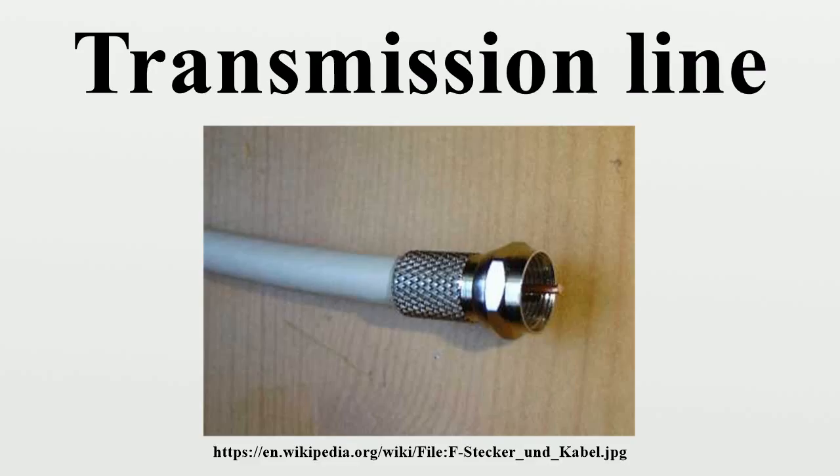Twin lead consists of a pair of conductors held apart by a continuous insulator. By holding the conductors a known distance apart, the geometry is fixed and the line characteristics are reliably consistent. It is lower loss than coaxial cable because the wave propagates mostly in air rather than the thin dielectric. However, it is more susceptible to interference. Lecher lines are a form of parallel conductor that can be used at UHF for creating resonance circuits. They are a convenient practical format that fills the gap between lumped components and resonant cavities.